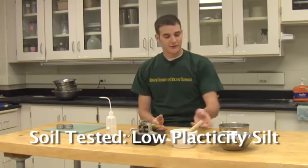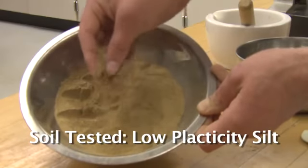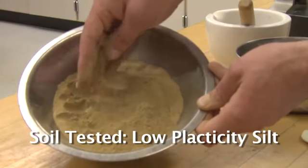ASTM specifications. The soil that we will be performing the limits test with today is a low-plasticity silt that comes from the Mississippi River Valley. This silt has been mechanically pulverized and then passed through a number 40 sieve to remove all large particles. For the purpose of today's lab experiment, bentonite clay has been added to increase the plasticity of the soil.